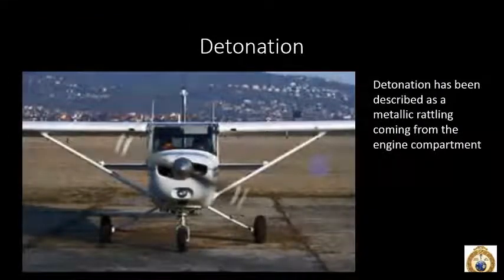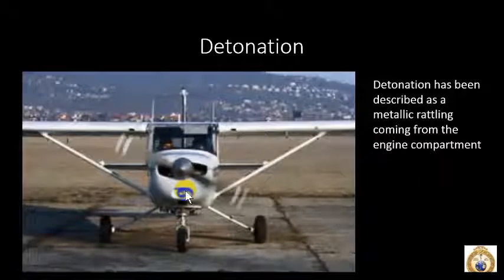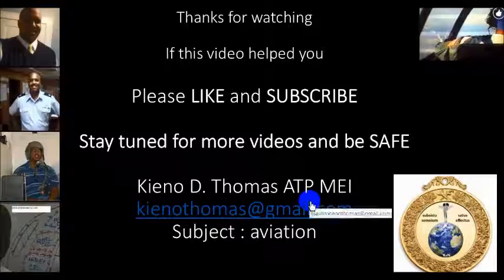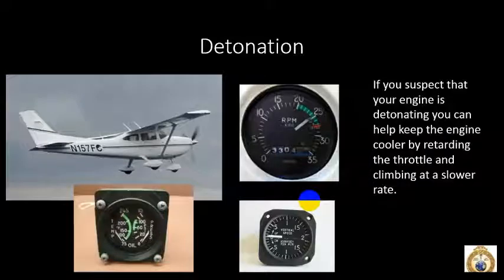Detonation has been described as a metallic rattling coming from the engine compartment. So these guys may hear like a tapping or something like that. And that is not something you want to hear before takeoff. You might want to shut the plane down.